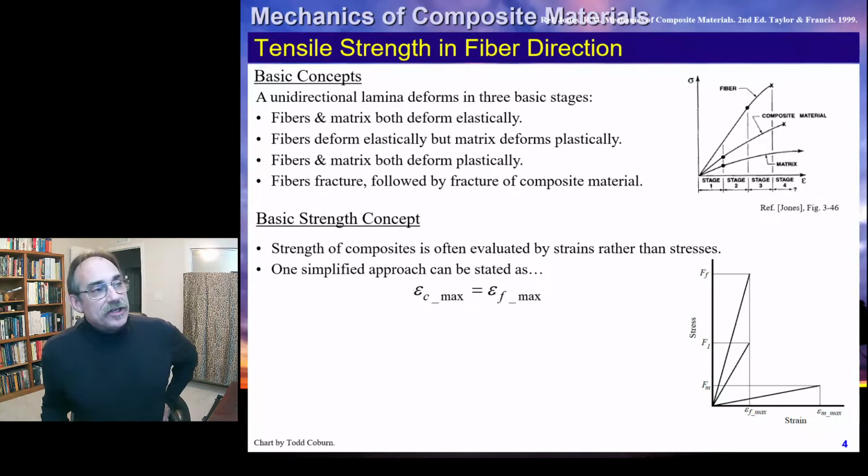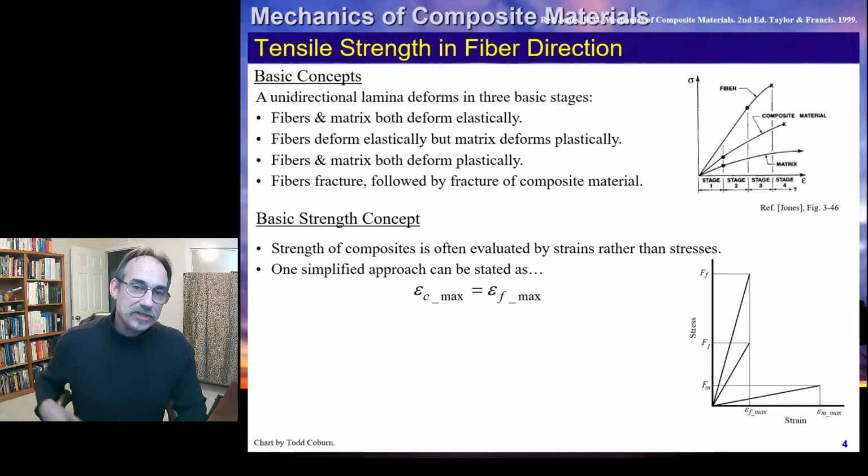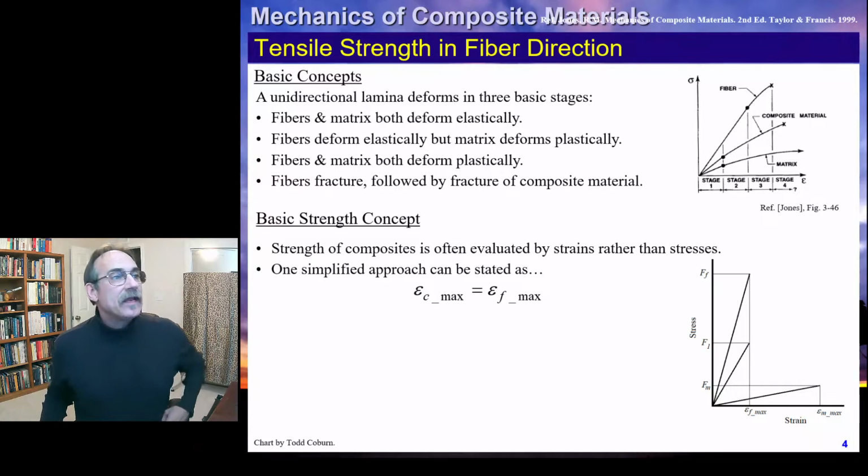And while it is, it's also common that a lot of folks prefer and feel it's more accurate to evaluate strains in composites rather than stresses. There may be some merit in that, but actually the stress approach, and stress is proportional to strain, at least the way we're simplifying everything in these cases, stresses are a little more intuitive for people, because that's what we're dealing with. And you can actually get the same results for most practical analysis.